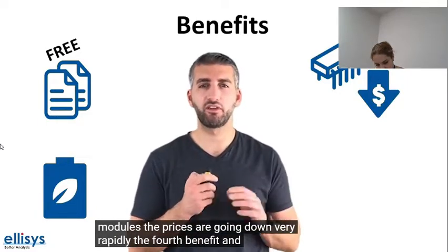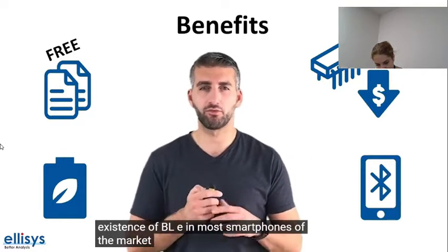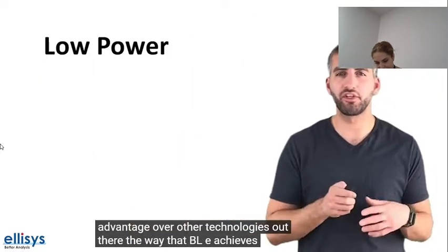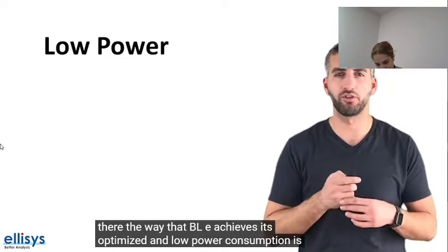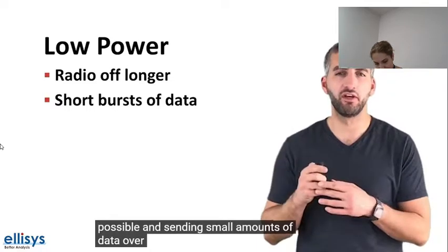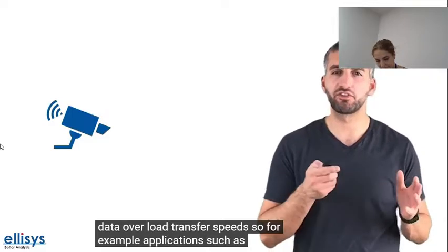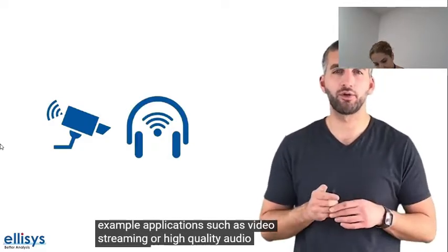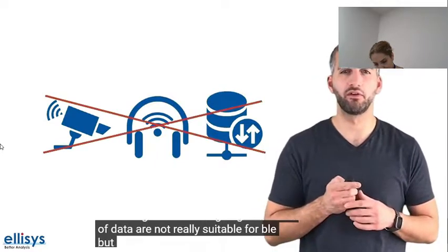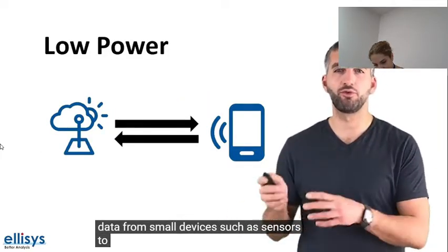The fourth benefit, and probably the most important one, is the existence of BLE in most smartphones in the market, which really gives it a huge advantage over other technologies out there. The way that BLE achieves its optimized and low power consumption is by turning off the radio as much as possible and sending small amounts of data over low transfer speeds. So, for example, applications such as video streaming or high-quality audio streaming or transferring large amounts of data are not really suitable for BLE, but rather it's meant for transferring data from small devices such as sensors to a smartphone.